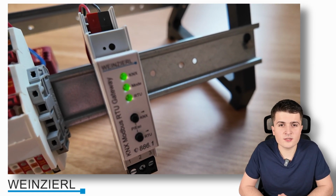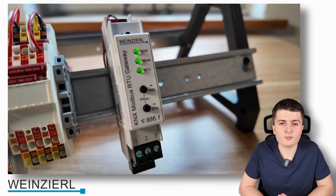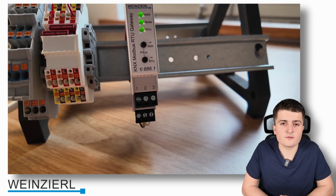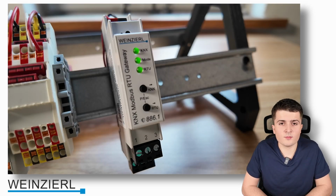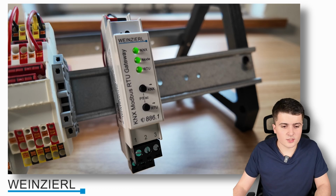So now let us connect the Modbus RTU Gateway into our KNX system. Therefore I have it already connected to the KNX line and also connected it to my Modbus RTU devices. In my case here I will use 2 energy meters. The terminals for the Modbus RS485 line are internally bridged, so that means that you can use one terminal for the Modbus RS485 line and the other terminal you could use, for example, for a terminating resistor. So now let's jump into the EDS.